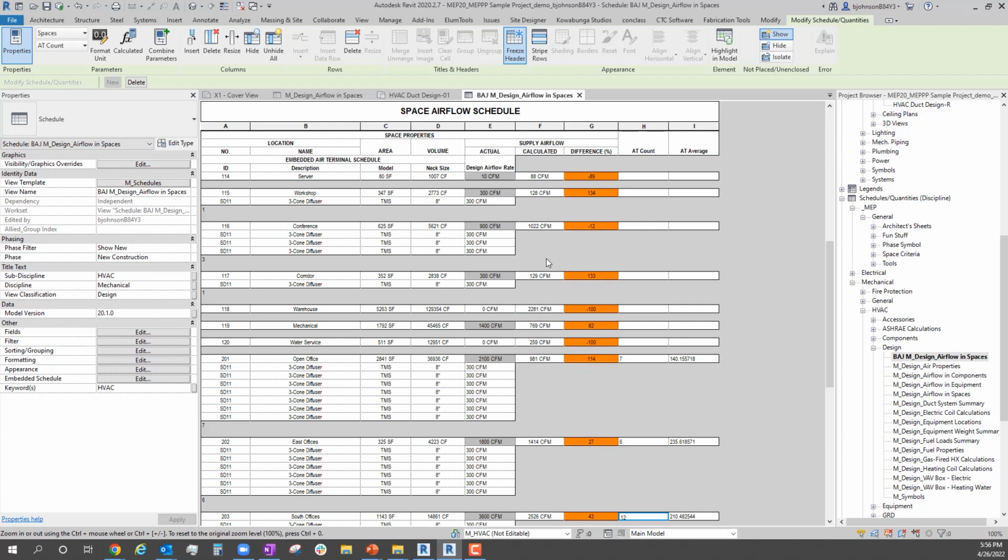So what if I go in and place all those air terminals and not care about the CFM at all? What if I leave them 0? All of them are then 6-inch neck sizes, right? Until proven otherwise. And I can come into this table after the fact and go through and add my counts after I've run heating and cooling loads, so I get the calculated supply airflow. That fills out all those fields. I fill in my counts, and then I go back and resize all my design airflow rates so that they are now the actual ones that I really want in there. How close are we to having 100% DD on our air terminals at that point? How many more changes are we going to have to make to those?